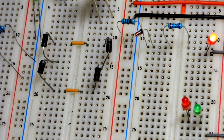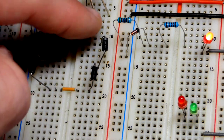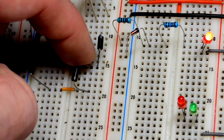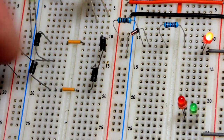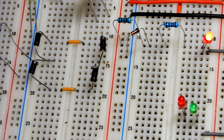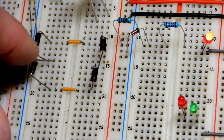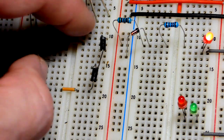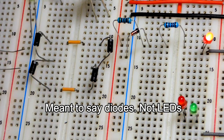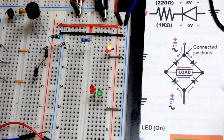You can see here, looks like the light's pretty good in this spot, that we've got the gray stripe away from each other with those two, and then the anodes, the gray stripe is the cathode, the anodes are connected directly together. They're offset by one spot. With these, there's no connection there. We've got to connect with components. But here we have the anodes facing away from each other. Cathodes connected to each other right there. And then the two sides of the LEDs, they're connected on both ends, as you can see in this schematic. So I just swapped the directions there.